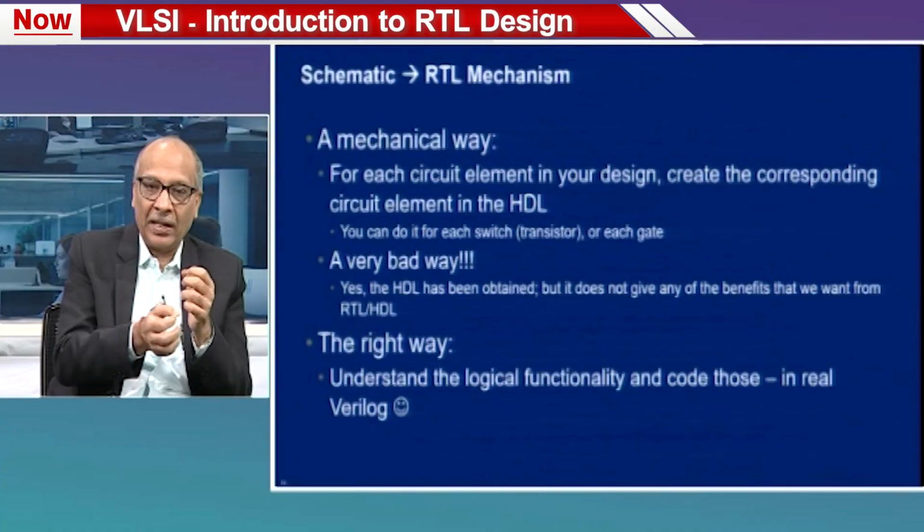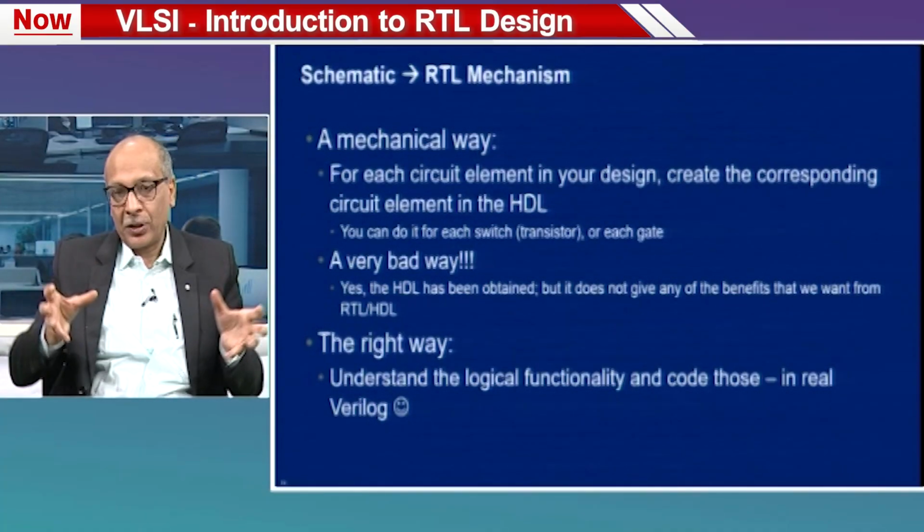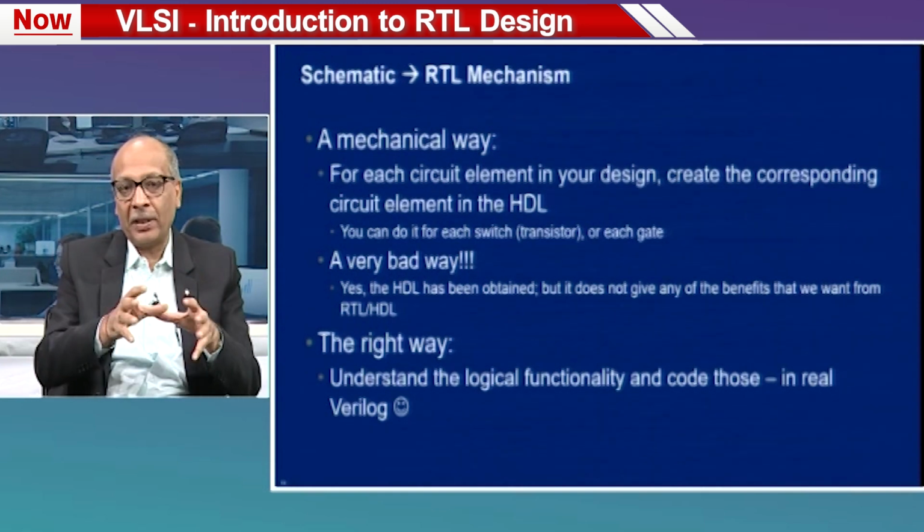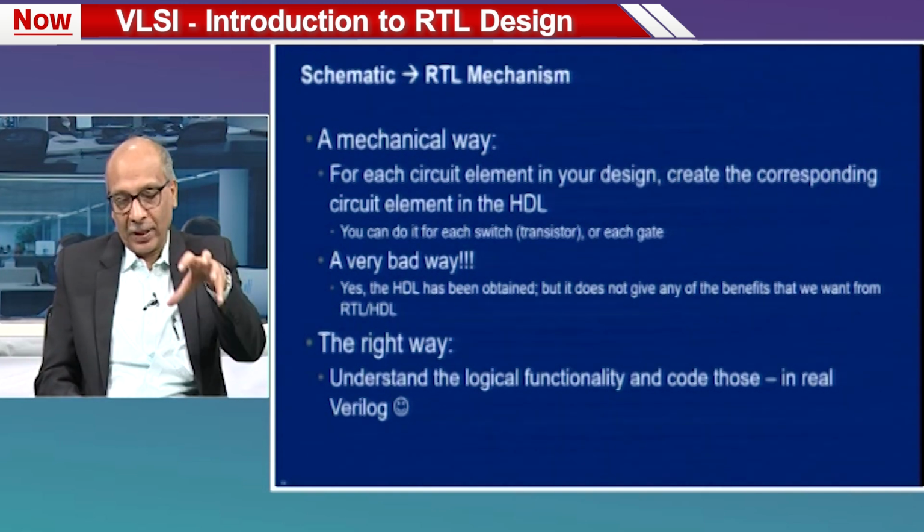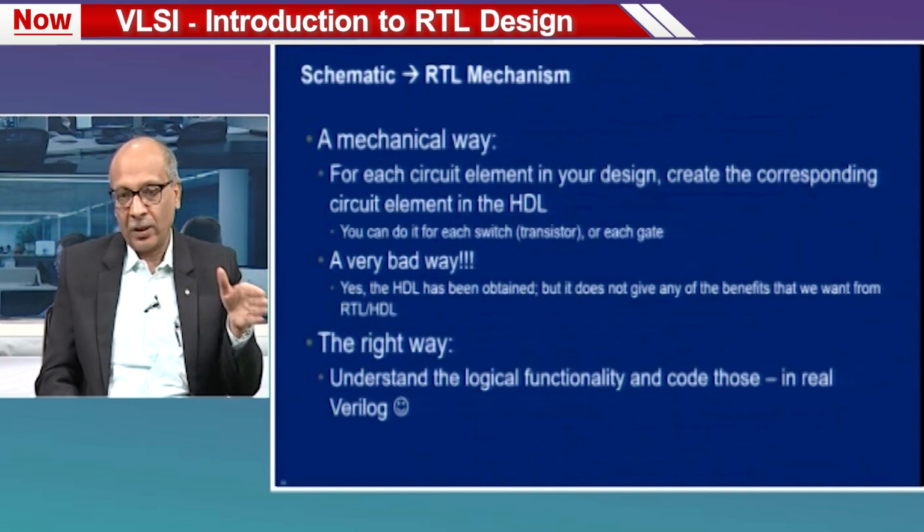The benefits we talked about earlier were being able to make use of the synthesis tool, and being able to write code which is easy to understand. But if it is still switch level, it is not easy to understand. So, the right method is to understand the logical functionality of that schematic and write the actual RTL for that logical functionality. Instead of doing element by element translation, understand the big picture and write the RTL for that big picture. Once you have the big picture captured through the RTL, now you can go through the RTL based design methodology.